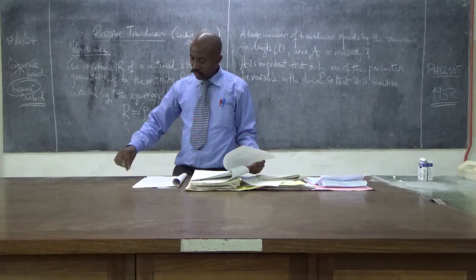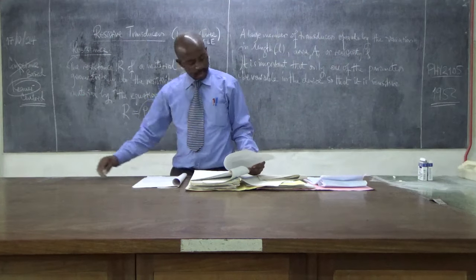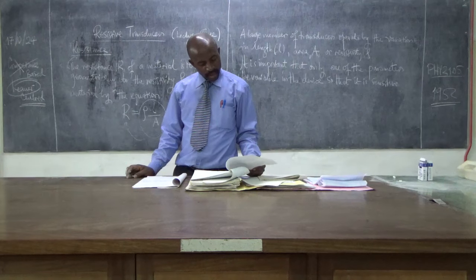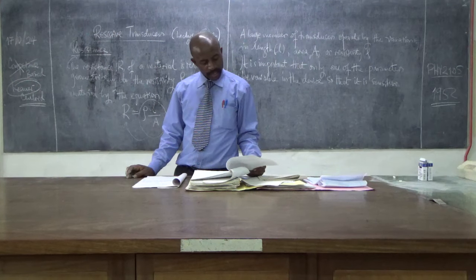Photo etching is where you use a machine to print the pattern, and it is then mounted on a resin film base, and the film backing is then attached to the structure with a suitable adhesive. This gauge should be positioned so that its active axis is along the direction of the measured strain.